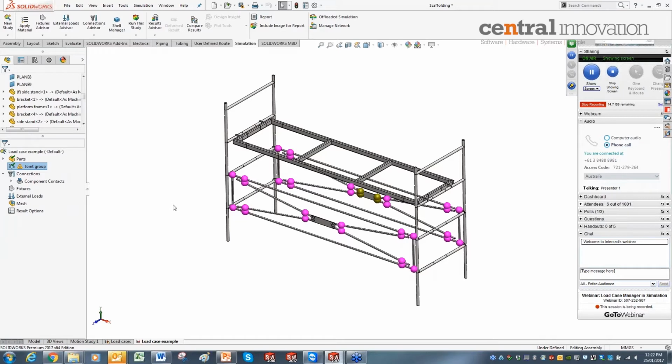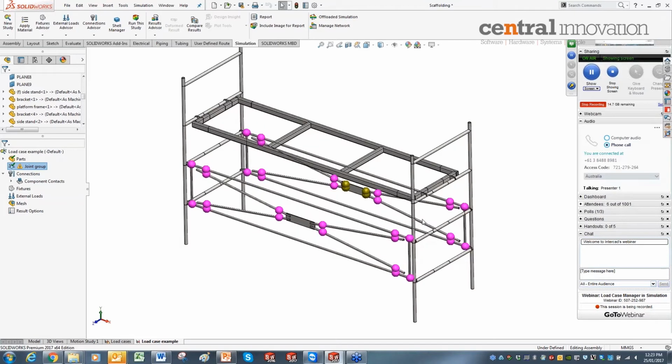Okay. In the next step, I have to define the contact condition, contact sets. Okay, I'll tell you the contact condition. These tubes are welded onto this plate, so I can create a bonded contact condition. And then most of the beams are welded. Again, I can create a bonded condition between 2 beams, between a face and the beam element.